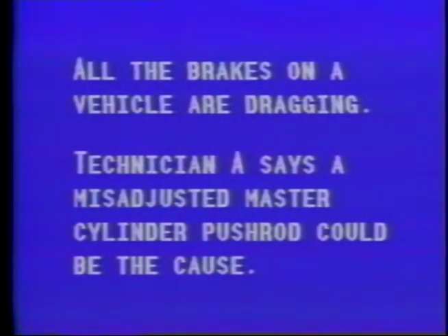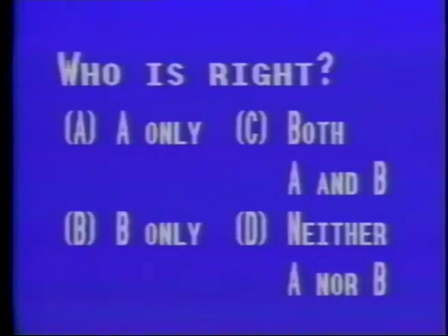All the brakes on a vehicle are dragging. Technician A says a misadjusted master cylinder pushrod could be the cause. Technician B says a misadjusted brake stoplight switch could be the cause. Who's right? A only, B only, C, both A and B, D, neither A nor B.